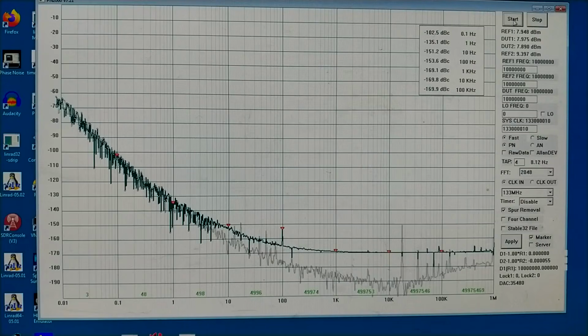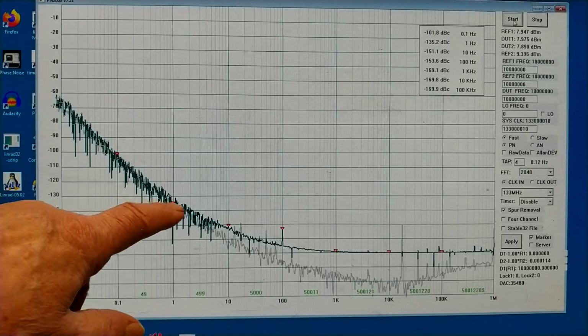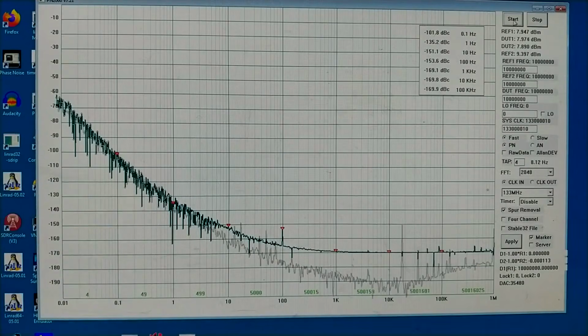And I've done this to verify that the noise is not caused by the amplifier. And this is the result at the main output. And it is below minus 135 dBc per hertz. There are still circles in the data points here, so it has not converged yet.